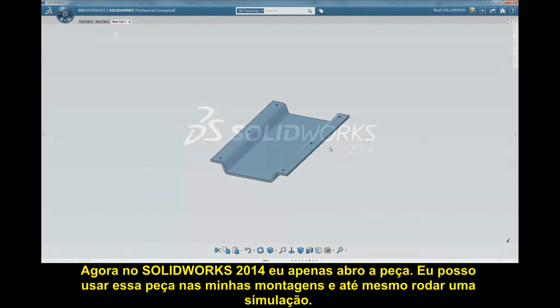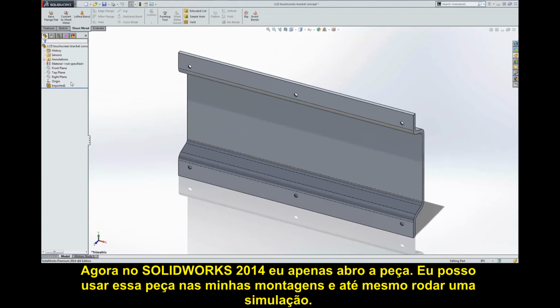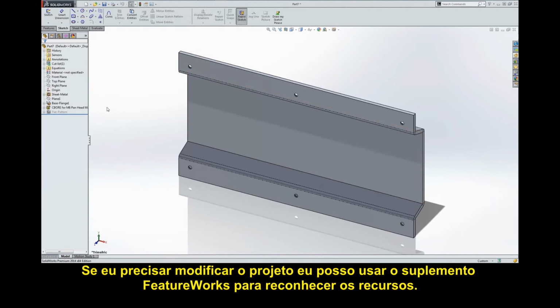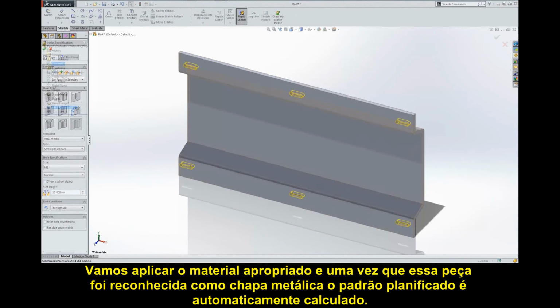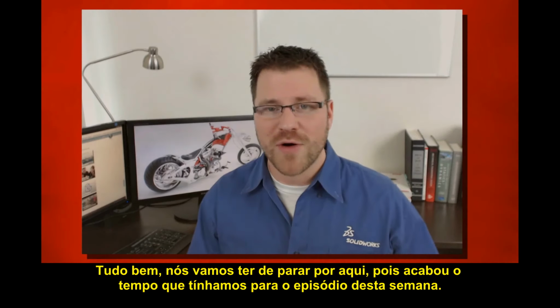Now in SOLIDWORKS 2014, I just open the part. I can use this part in my assemblies and even run a simulation. If I need to modify the underlying design, I can use the FeatureWorks add-in to recognize the features. The M6 mounting hole pattern is recognized as a Hole Wizard feature. We'll edit the holes and change them into slots. No problem. Let's apply the proper material, and since this part was recognized as sheet metal, our flat pattern is automatically calculated.